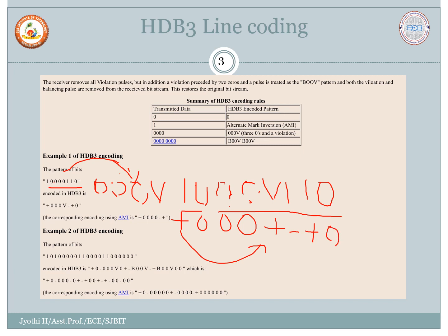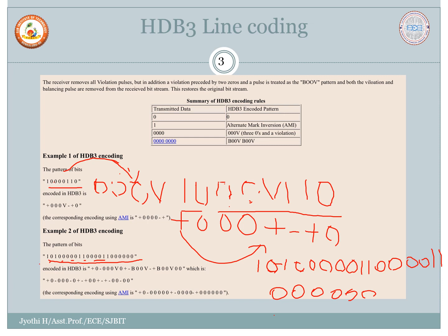Now this is the electrical waveform. The polarity of the bit stream becomes plus 0 0 plus minus plus. This can also be drawn in the form of a waveform. Plus is the positive value, then 0 0, 0 0, then again positive, again negative, again positive, and this is going to be a 0.